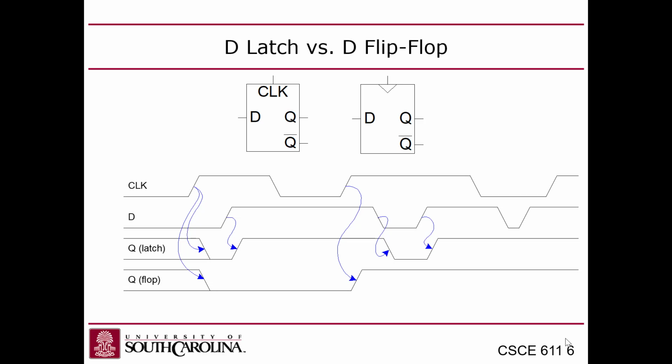If you're not careful, though, you can accidentally write SystemVerilog that infers the behavior of a latch. And if you do that, you'll actually get a warning message when you go to compile your design in Quartus. I don't know if ModelSim warns you for that, but I know Quartus does, although you might miss it because it outputs a lot of stuff. Any questions about this?